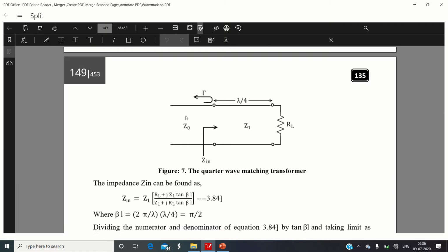See the figure here. On the left hand side, there is a generator. This generator is connected to a load impedance. The load impedance is on the right hand side, and we observe clearly that the load impedance is a real value, indicated with RL. Please remember that this quarter wave transformer technique is only utilized when we want to match a real valued impedance, so this impedance only has the real value, that is, a load resistor.